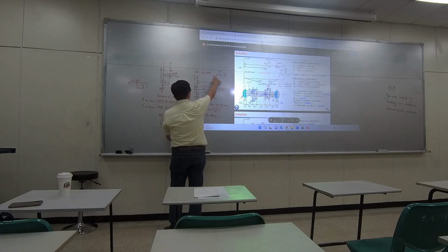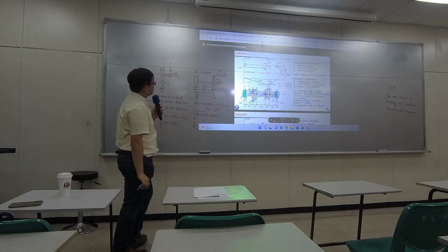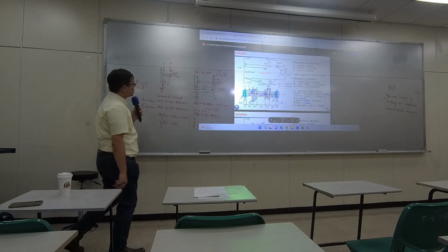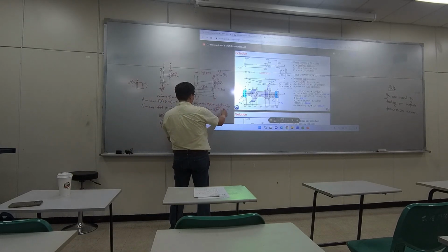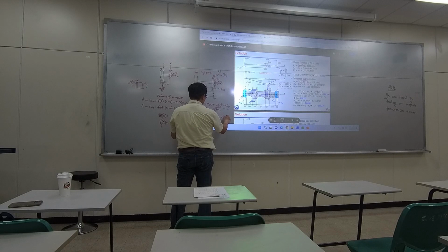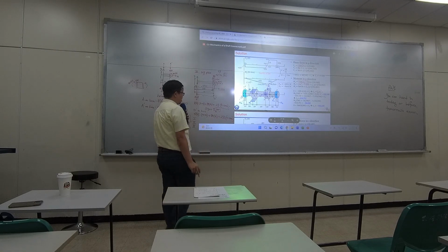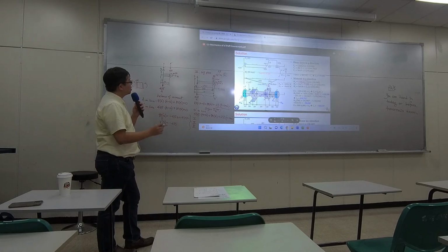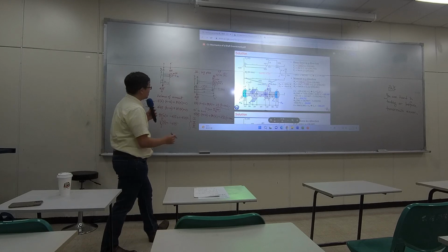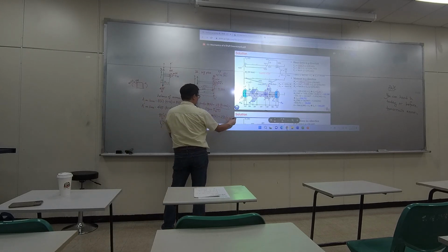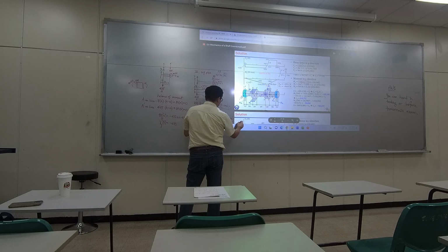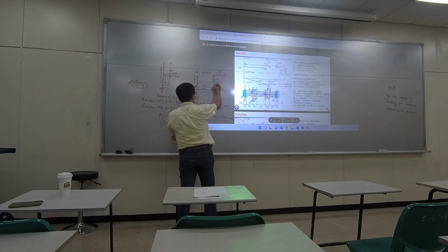The clockwise will be the one contributed by the distributed load, and we already tried this earlier. So basically 28 times x minus 240, that would be how much equivalent single load you have. Multiplying the small distance right here is gonna be a half of x minus 240. Just a tiny distance right here, right?